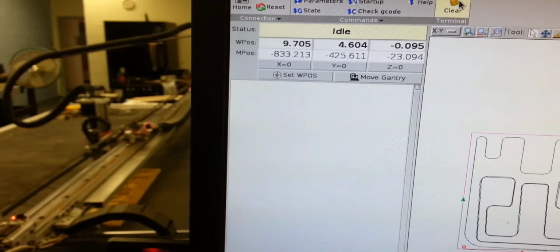That's the lowest I think I've seen it start. Normally it starts at a really high random line number, and I don't know why. I think part of it is because of this G90.1. Grbl doesn't like it. It only likes G91.1.